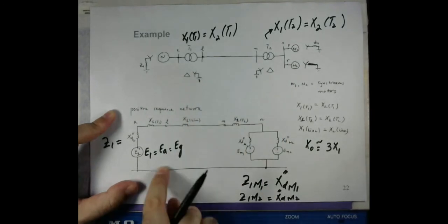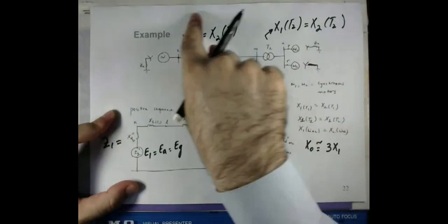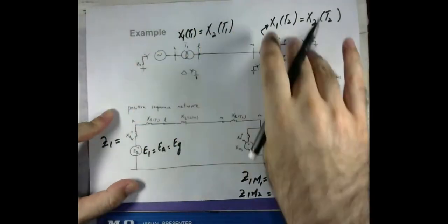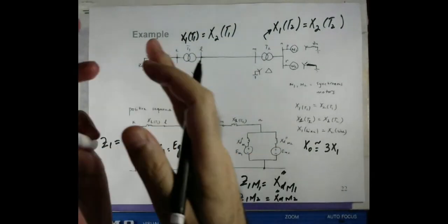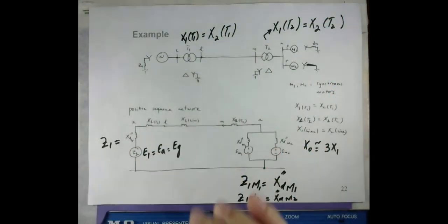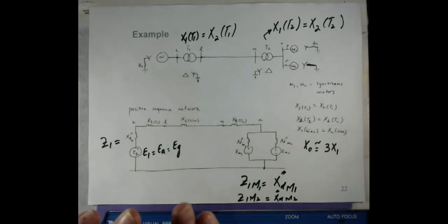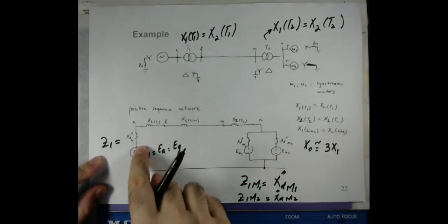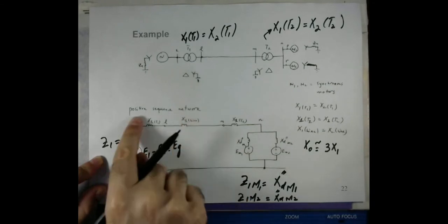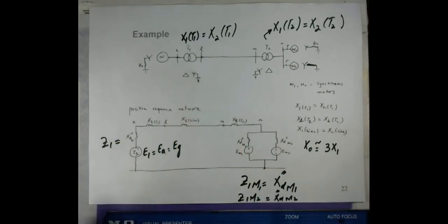So this is now the positive sequence network for this whole arrangement, or for this particular network where we have generation, transmission, and utilization. So this is now the positive sequence network, where we have only considered the positive sequence impedances, and we also considered the sources, because we are discussing the case of the positive sequence network. Now let me also draw the negative sequence and the zero sequence